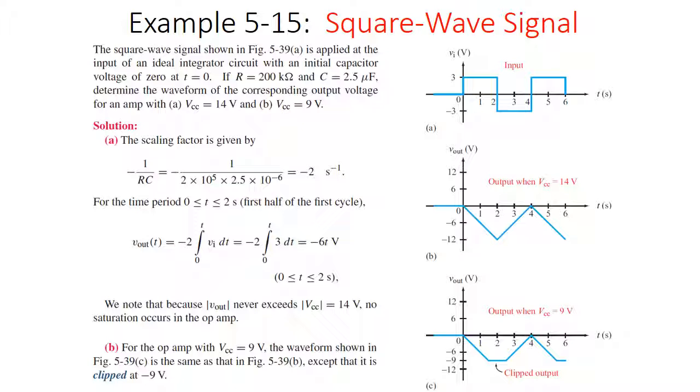And so as long as we're going through time, you're going to multiply minus 6 by t, and that's going to give us a ramp function down, which makes sense. It's what we're looking for. So if we look at the integral for that step function, we're going to get those ramps. So from 0 to 2, it's going to go as a slope minus 12 down and 2 over, and that's how we get our first slope down in picture B. And now we can repeat this again and again for each one of those other ones.